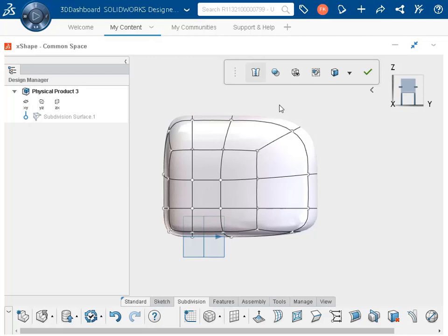First, box select over the vertex in the upper right corner of the model. 2 vertices are actually selected. The robot appears, but it is oriented differently. This is because it always aligns to the full set of selected geometry. Dragging the planar section of the robot allows you to drag along the plane formed by the 2 adjacent axes. I'll push the vertices inward, reshaping the outer edge of the surface.